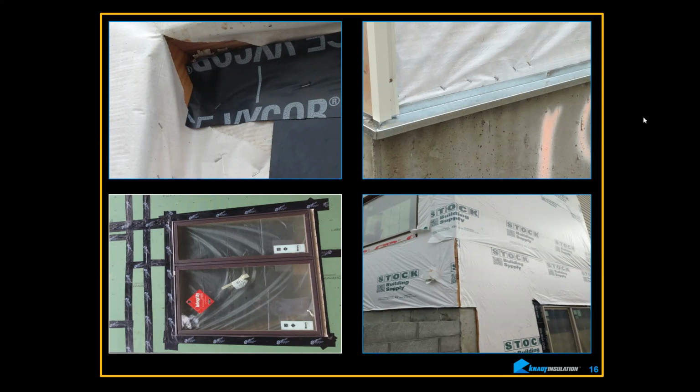There really isn't an inspection that I know of for a weather-resistant barrier, and that's a problem. So this is a problem right here. They're already siding the other side of the building when I took this. This is a problem here because the tape is installed incorrectly, specifically on this side. This one goes over this one, and this one should be shingling over that one. So who knows why they do the things that they do. Gaps right next to the concrete.